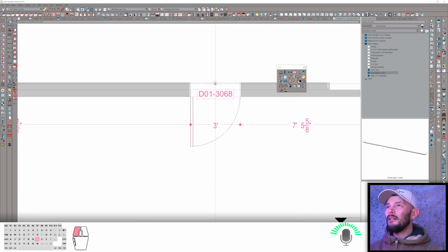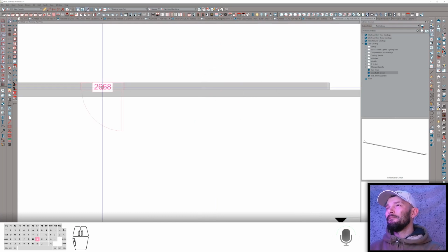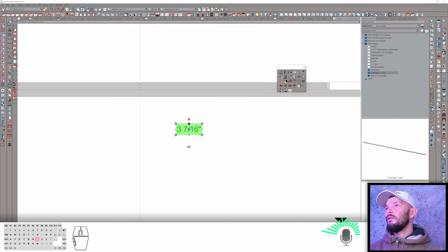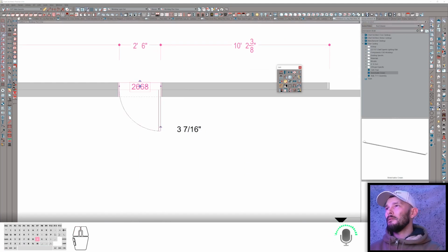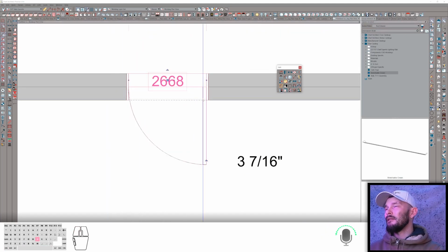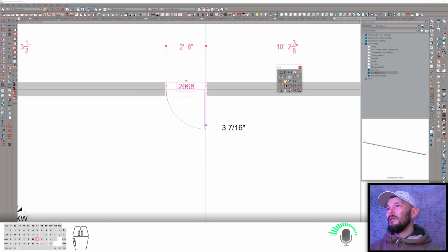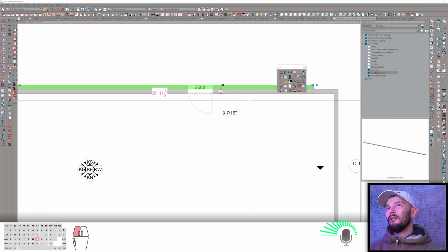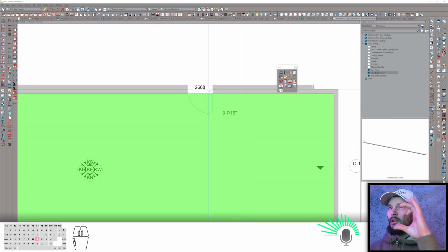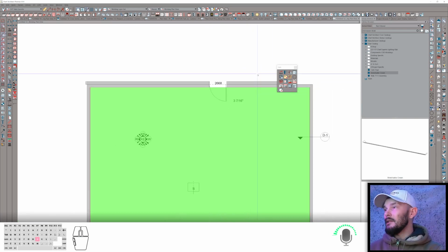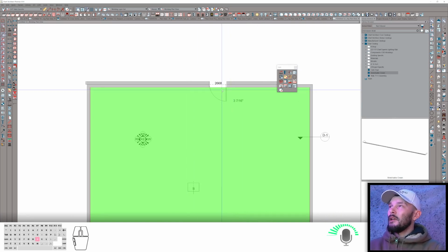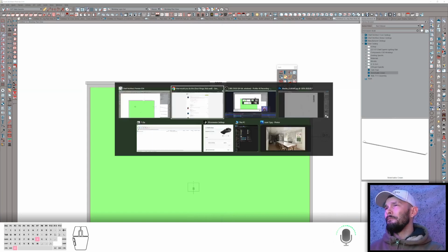Just a couple tricks there. We can, of course, put it on that outside assembly. We can have it recessed. We can flip it, rotate it, flip the orientation. There you go. See, now it's recessed and it's inside of that second wall assembly. And then if you remove any kind of lines in between this, you could still get a solid looking wall, and then show your default wall types in a detail or something like that, which is what I do. Or show your full layer stack, who cares, right? It totally depends, up to you.